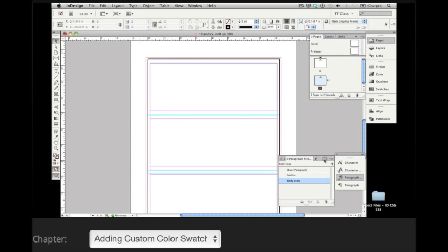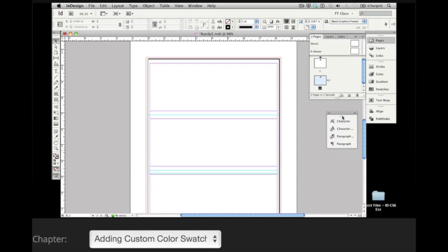I'm going to shrink this back into the group, and then I'm going to go to those 2 double dots just like so. I'm going to hold the mouse button down, and I'm going to place this between the swatches and the text wrap buttons in the side dock where it was originally at. So as I move my cursor inside of here, if I let loose of the mouse button right now, it would place all of that between Align and Pathfinder. If I want to place it between a group, I want to get to a spot where I see a narrow line between the panel groups just like so.